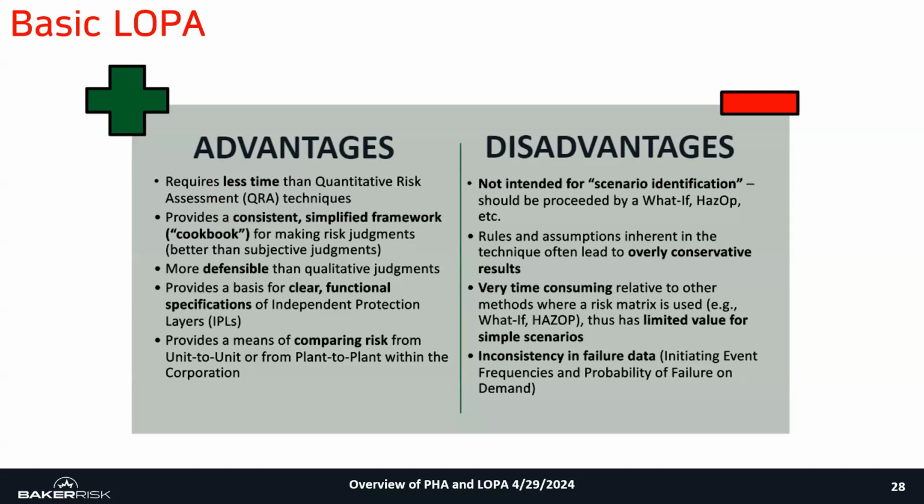In some instances, the rules and philosophy with LOPA may be overly conservative, or, honestly, it may not be conservative if your process has failure rates that are higher due to the service or nature of your process. That could be underestimated.